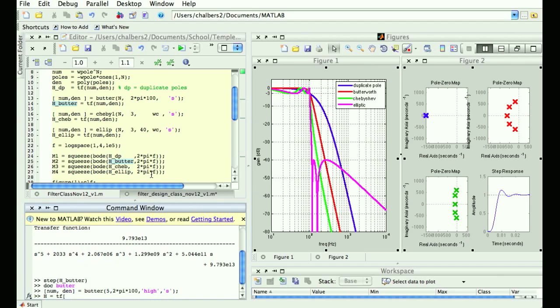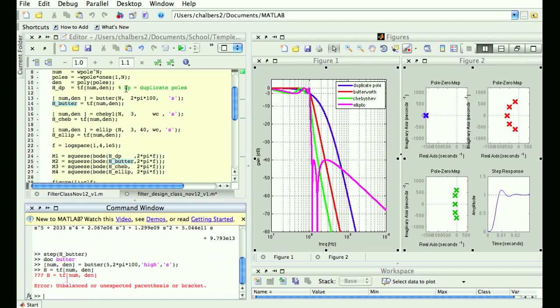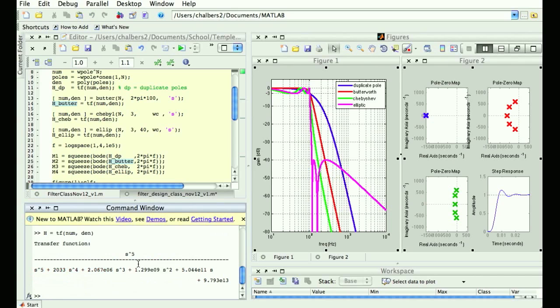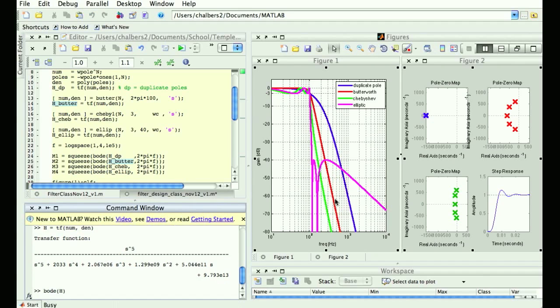And look at that. What do I got? High pass Butterworth filter with a cutoff frequency. Oh, it gave me my cutoff frequency. It plotted the axis in radians per second. If I right click, I think there's a way to twist its arm. Properties. I'd like my frequencies in hertz. Kilohertz? Look at me living the dream. Okay, let's put a grid on there. And I've just built myself a high pass filter.